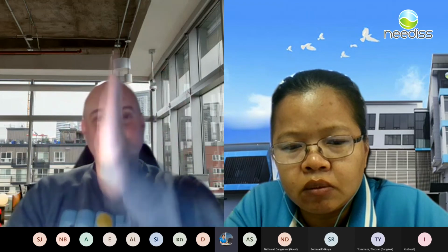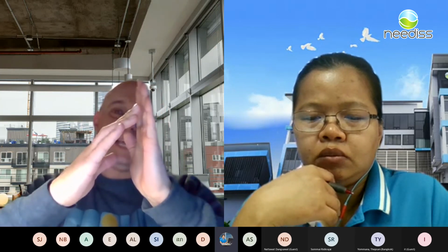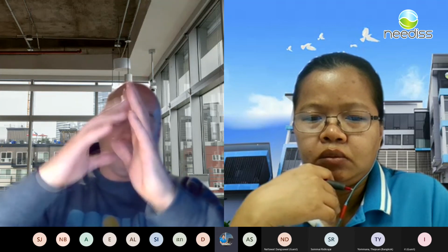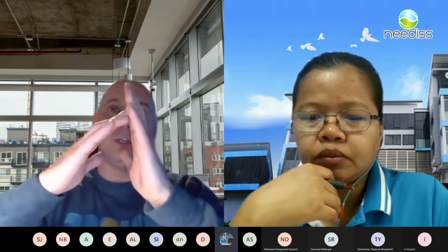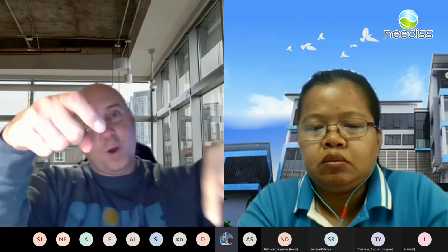the flow is on an angle, so if we think of this as normal, and we think of this as what we discover in the stack, then theoretically, yes, if we figure this out and we want to do a Method 5, our Method 5 should be done on the angle like this. So the probe, the nozzle won't be in the stack directly like this. It may be turned like this. And we're actually going to be measuring the flow coming directly into our probe. That would be the best option, like this.